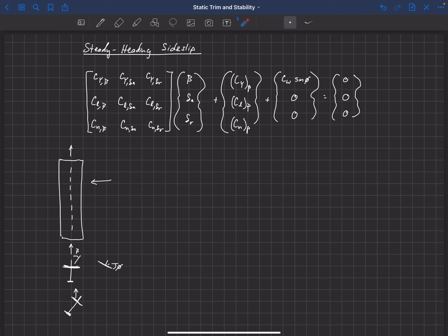So let's look at the mathematics behind this. In this case, we've got a velocity that is just above our stall velocity, some velocity that we're trying to land at. And then we've got some crosswind velocity. What we don't have control over here is beta. We have very little control over that. We can crab in, like I said before, but in this case, we're going to treat beta as a known value. And so we're going to rearrange these equations a little bit.